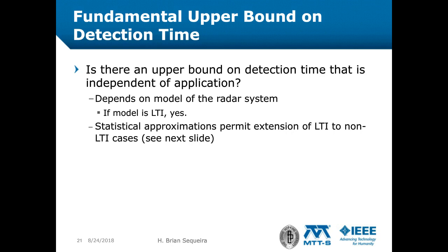Why? In a linear system, the amplitudes of all spectral components of the input signal must be scaled by the same factor. Their phases must be altered in linear proportion to their frequencies, and no spectral components should appear at the output that are not present at the input.